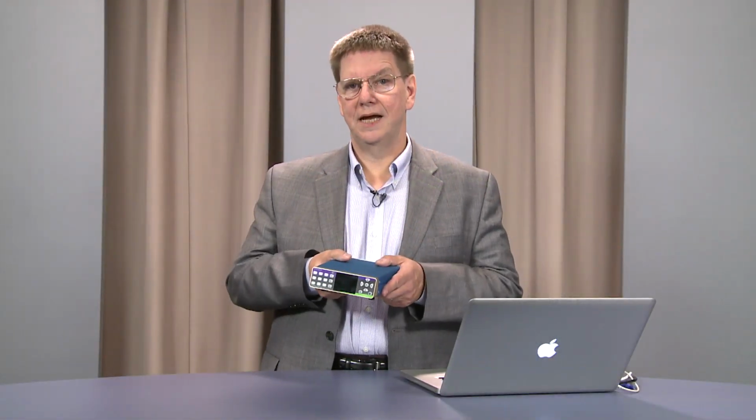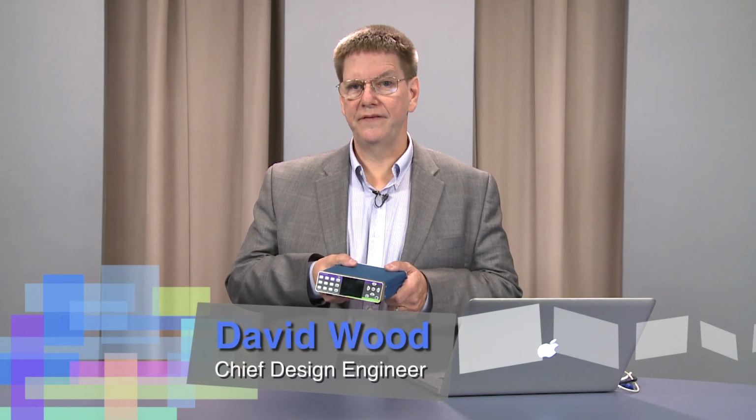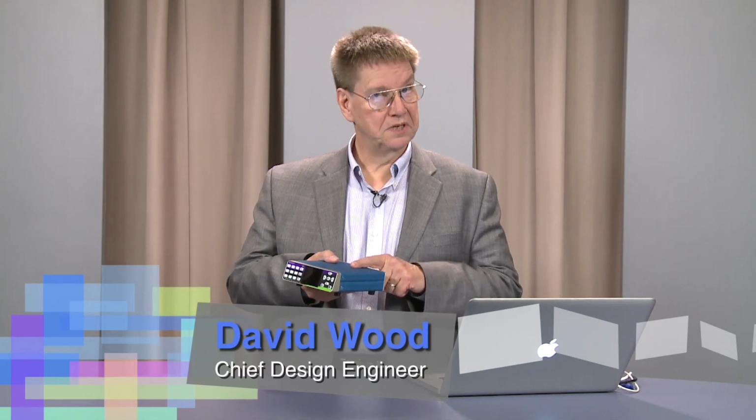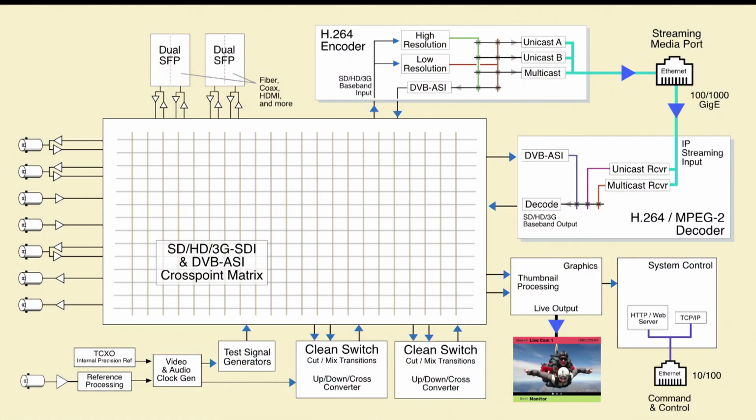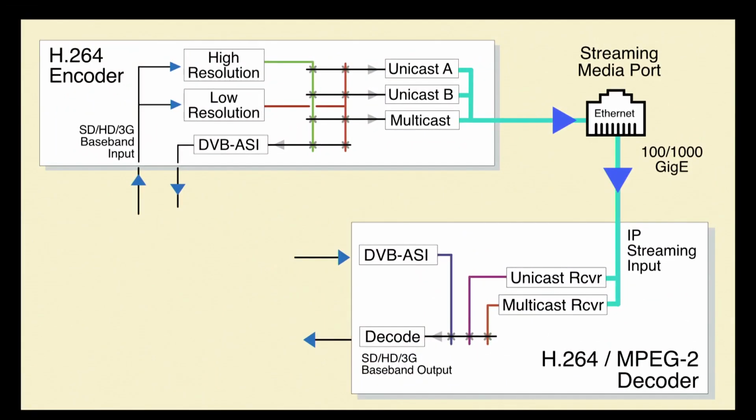The Ensemble Designs BrightEye NXT 450 Clean Streaming Router. Despite its compact size, it contains both a full-featured encoder and a decoder. Let's look at the architecture. At the center of the NXT 450 is an SDI crosspoint matrix. It connects all of the resources: inputs, outputs, clean switches, test signal generators, and an encoder and decoder.